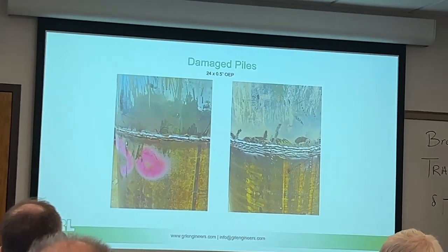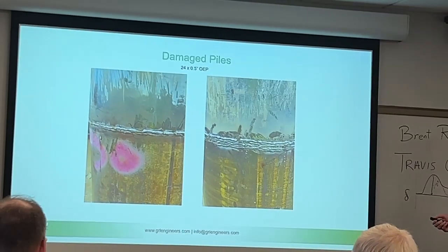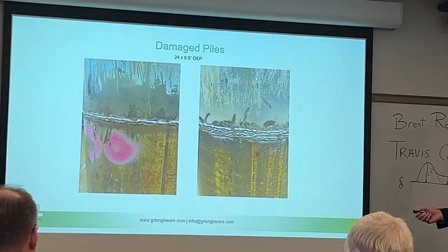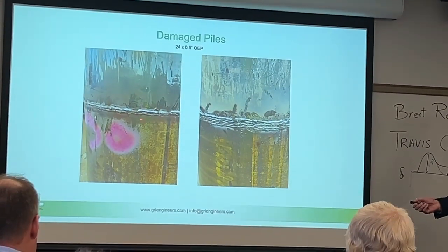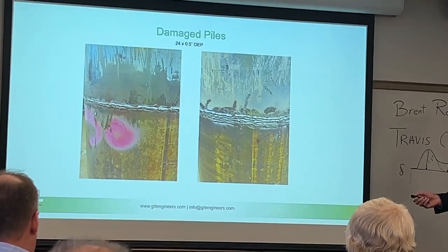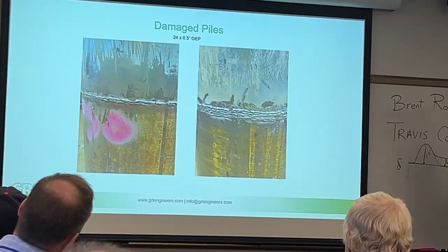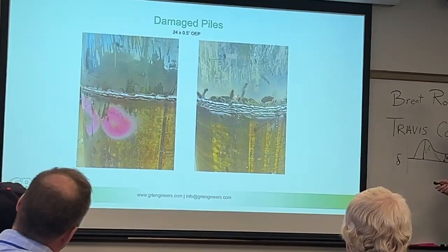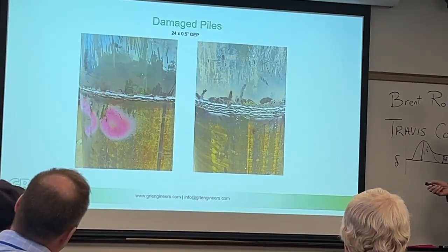What you see here on the left was a video. This is the welds that the welder was performing. This is not the weld that broke. This is another one of the welds that he had done. You can see that another welder is coming, and there's a series of these little markups he's put where he's not so happy with those welds. And here is welder number 2's weld, actually that same pile. So they rooted all this out, cleaned it up, and he did it again.